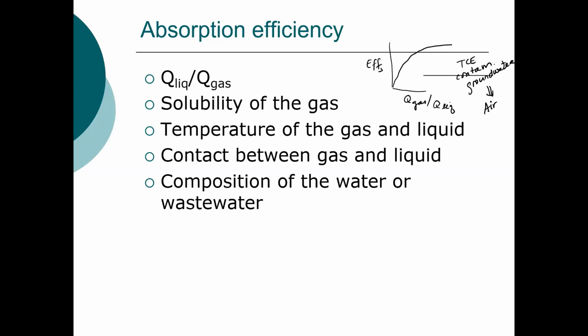And you can think about this in terms of a river. If we're looking at the mass transfer of oxygen from the air back into the water, think of the Red Cedar. Is this mass transfer rate going to be more efficient in areas of the Red Cedar that are very quiescent, slow moving, or an area of the Red Cedar around the rapids behind the admin building?